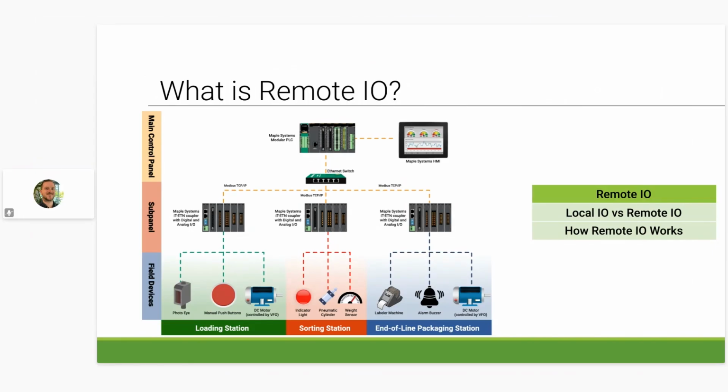Remote I/O allows applications to be set up in the most effective manner where users will not have to worry about reduced signal quality or expensive and overly complicated wiring requirements. In addition to this, the maintenance of remote I/O is much simpler since users will not have to trace long cables to isolate an issue. Also, remote I/O is great for extending the already existing local I/O within the same cabinet. We will go over these types of applications in more detail later.